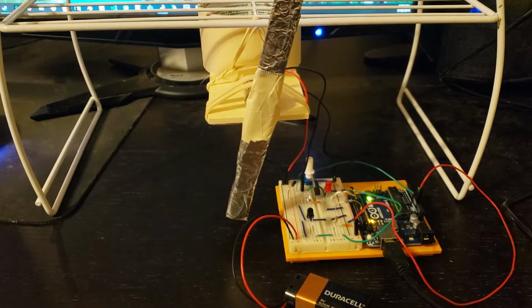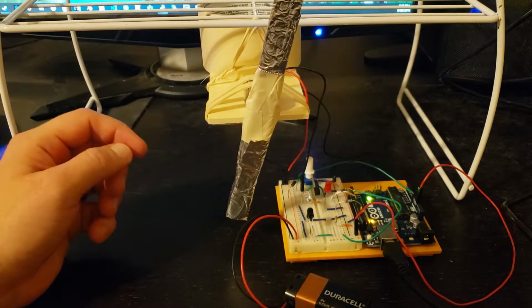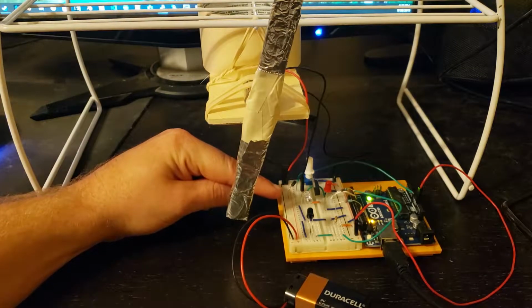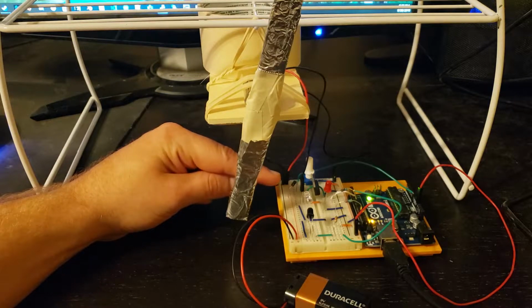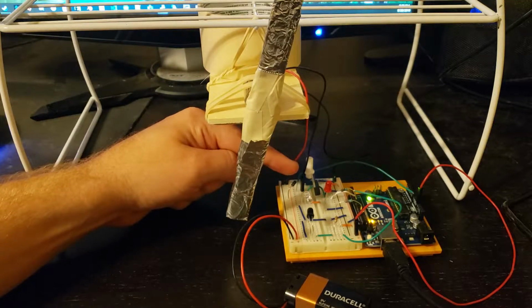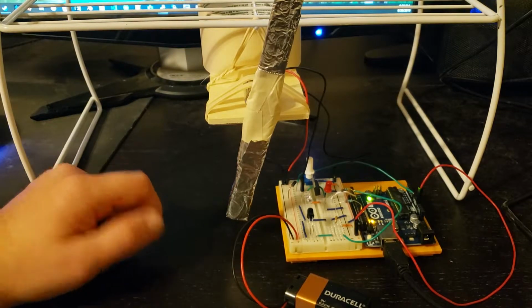While reading through the Arduino projects book, I found that I also had to add a diode around the DC motor, which protects the Arduino circuit from back voltage generated by the DC motor. That's a problem when you shut it off abruptly. You'll see the diode is right here, connected to the power, and it sits in between the ground and the power of the DC motor. The black wire next to it is the ground of the DC motor up here. After I had that set up, I was able to turn the DC motor on and off, but I still needed to be able to control the DC motor's speed to mimic the Beekman motor.